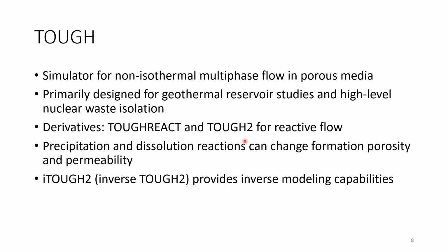Again, there is also an inverse version. So just as Hydrus is specialized on unsaturated flow, if you're talking about chemistry and complex multi-phase scenarios, which go beyond what you can do with FEFLOW, then TOUGH is a very good tool to take a look at, right? I have never used it myself, so I can't tell you much about the learning curve. But if you have to deal with those kinds of chemical couplings, this is a very hot recommendation to take a look at.